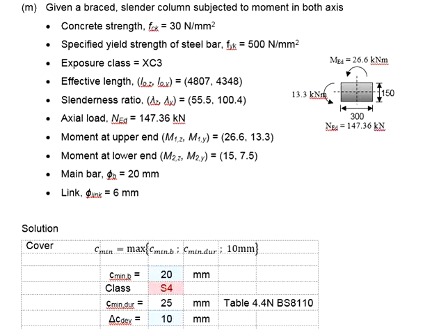Normally, designing the reinforcement bar in the minor axis will result in more reinforcement bar required. Therefore, you could consider increasing the B section, probably from 150 to 175 or even to 200. If you have no limits in terms of the column size, you can go for a bigger B.